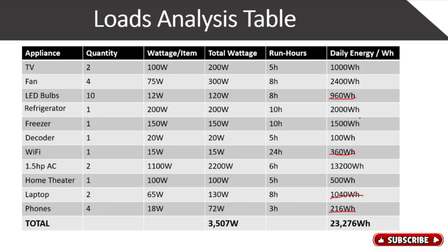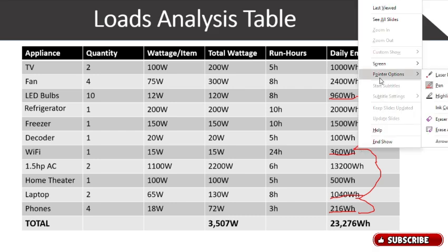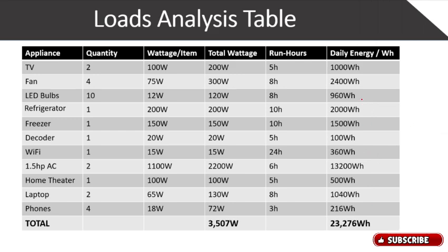Now if you do not include these, and you sum all of their energy consumption, you see that they are consuming more than 2 kilowatts of energy, which is very bad if you do not include them because you think they are too small. So all I'm trying to say is, no matter how small those appliances are, always include them. If you are not going to include those appliances, then make sure you oversize after everything.